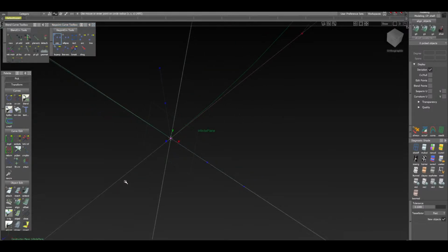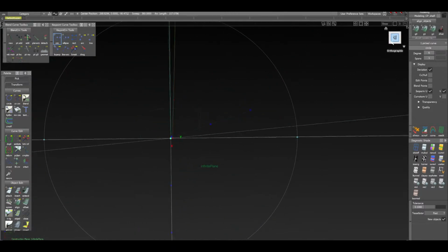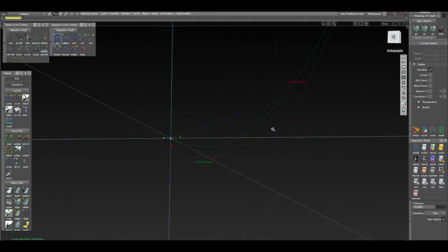And I'm just going to drag to that point. And I'm just going to type in 25, and that should work. 25, enter, and there we go. Okay, great. So we have a geometrically accurate circle that's just been built, 25 millimeters, which should match the tubular offset parameters that we established earlier. Yeah, okay, I just hit enter just in case. So now we have our circle, okay?